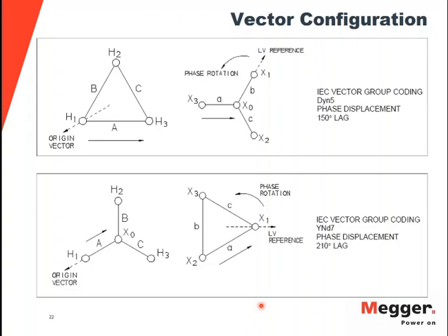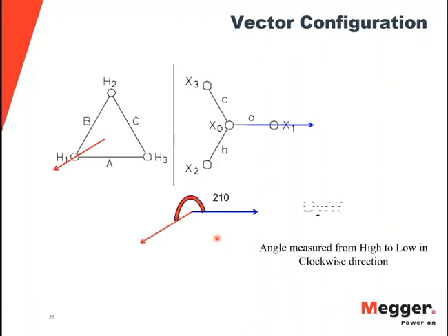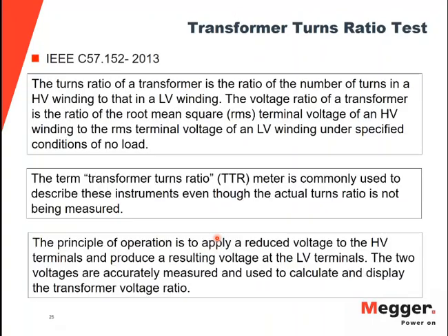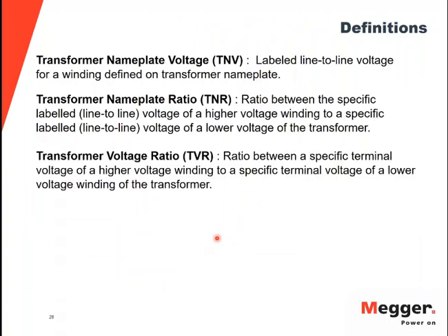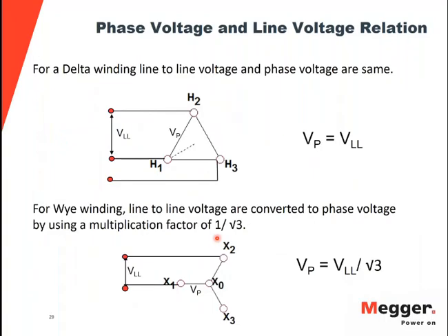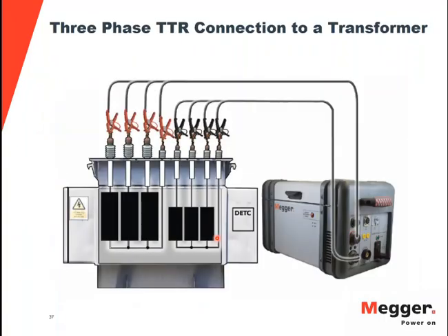Okay? So if you demagnetize your transformer, of course, you will minimize to a very low number this remnant magnetization in the core. And one of the things that is critical as well is not just for the energization of the transformer, but also for any additional testing that you may carry out on the transformer. If you did a winding resistance test, and after the winding resistance test, you will do some AC testing like ratio, excitation current, your leakage reactance, whatever the AC test will be next.